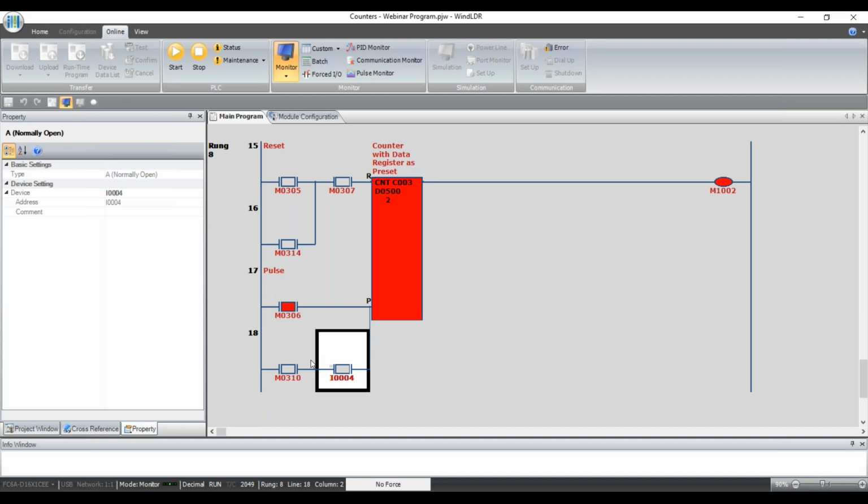My general rule of thumb is if I've got something that's turning on and off more than 20, 25 times a second, I'll typically go ahead and use a high-speed counter to do that. Again, that's just me. You can do the math and figure out what will work for your applications. What's the max pulses per unit these cards allow? Again, on the digital input side, it's 0 to 24 volt. The frequency is going to depend on your application, but what I just mentioned is the rule of thumb I typically go by.